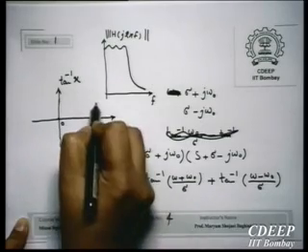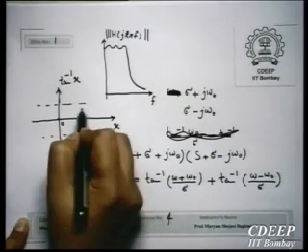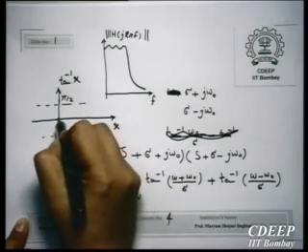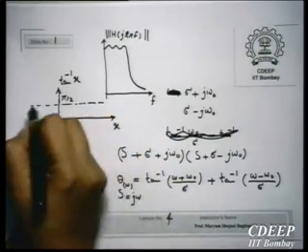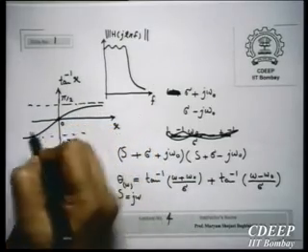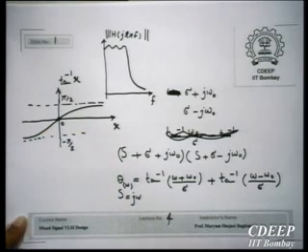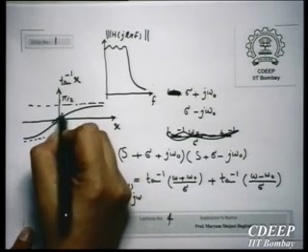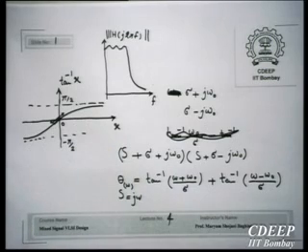as 0, it is 0. This is pi upon 2, minus pi upon 2. So it is 0. So now, if sigma is very small, it means that you are close to this region, which has the highest slope. So that is the reason we observe a rapid change in the phase when we are close to the pole. And when this pole is close to the omega axis, the real frequency that we deal with, which is j omega, is actually getting close to it.